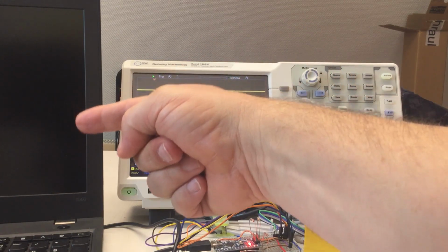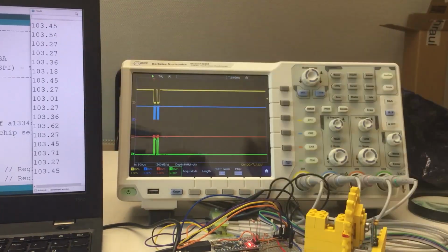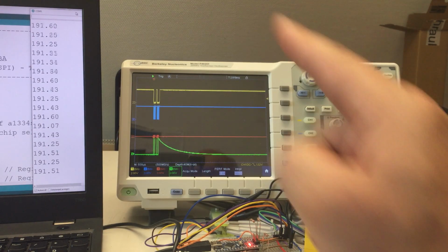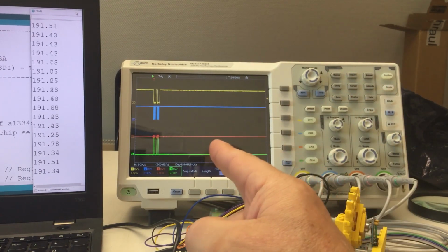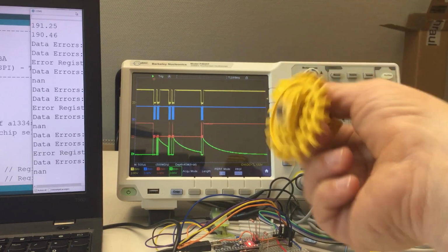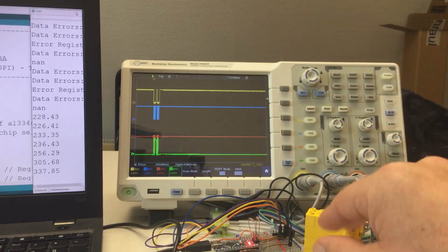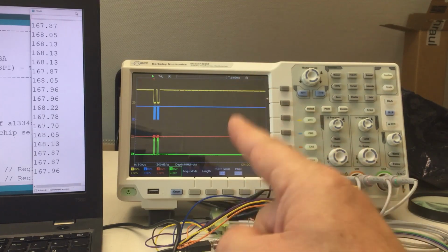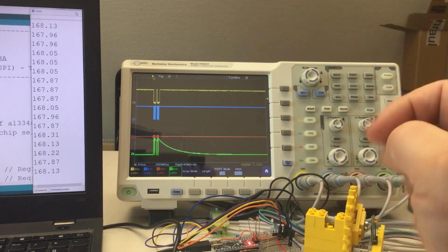And sorry, my notebook is in standby, but you would see here, well, yeah, we can do it. There it is. Okay, and hopefully everything is still working. Yeah, it is. Now, I also talked about resetting these error flags, especially the low power error, and we didn't have a low power error, we just had a magnet lost error. Yeah, magnet lost, somebody pocketed it. Resetting, where was I? Yeah, resetting that power lost flag is most important, because otherwise the chip won't work properly.